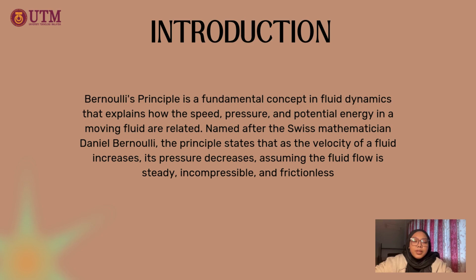So the Bernoulli's principle is a fundamental concept in fluid dynamics that explains how the speed, pressure and potential energy in a moving fluid are related. Named after the Swiss mathematician Daniel Bernoulli, the principle states that as the velocity of a fluid increases, the pressure decreases, assuming that the flow of the fluid is steady, incompressible and frictionless.